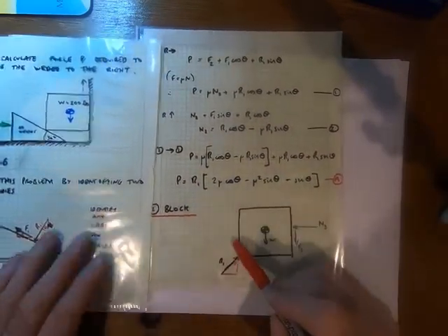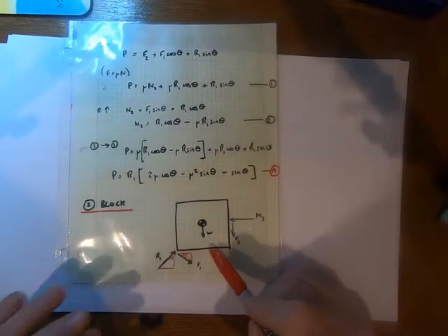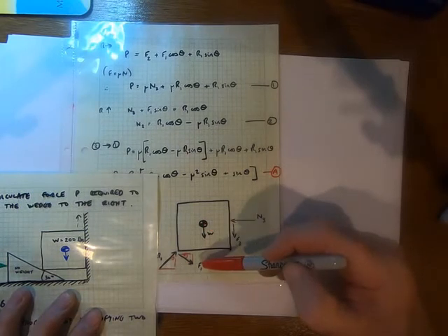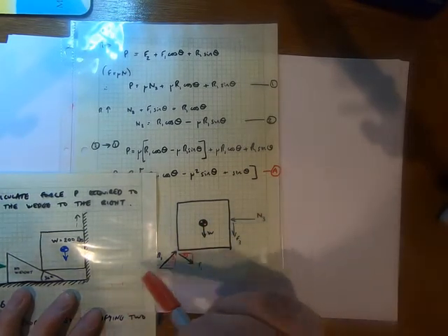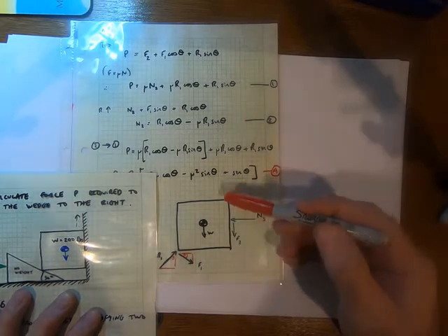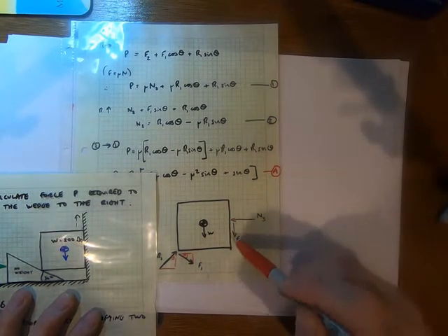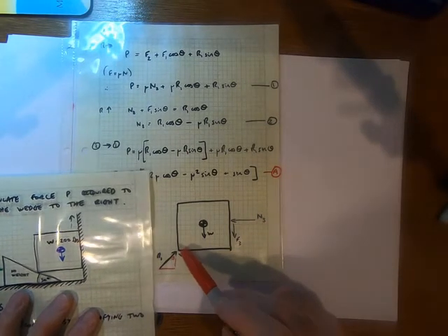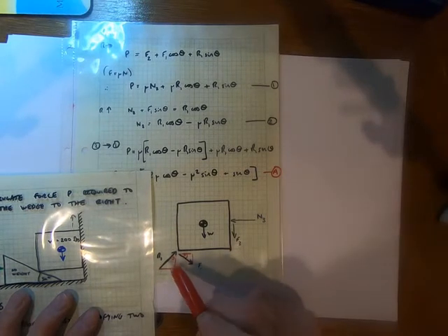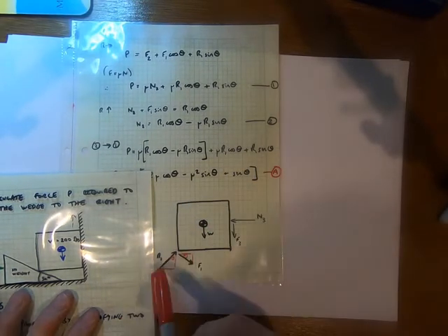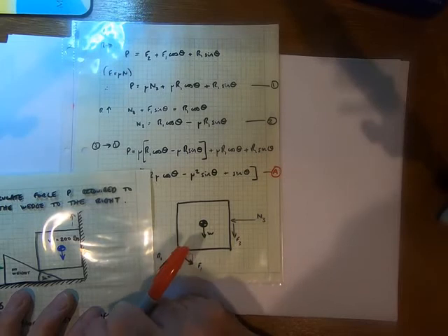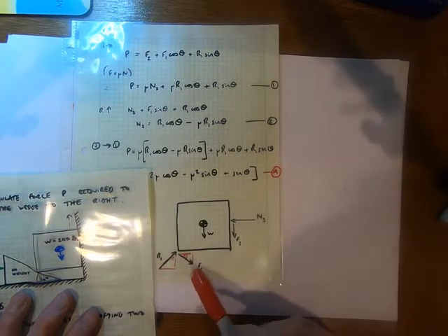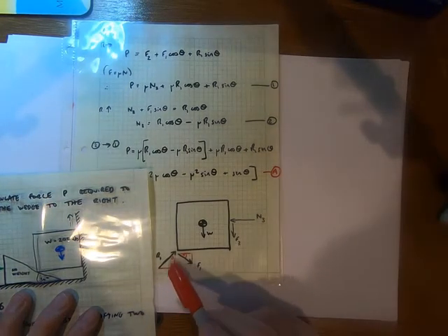Okay, so I draw my block. Looking at the block, and again going back to the original sketch, we've got the weight of the block shown. It's up against the wall. If we're pushing the wedge in, the inclination is that we think this would go up, so the friction is going to be acting down, F3. It's been pushed against the wall, so there's a reaction there, N3. And then at this point of contact, Newton's second law, equal and opposite forces. We had an R1 acting onto the wedge, so we've got an R1 in the opposite direction acting up onto the block. And then we had friction acting up the wedge, so friction here is acting down in the opposite direction. And then I've just brought in the theta angle.